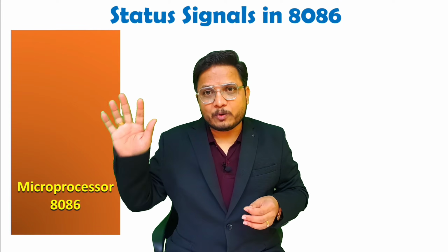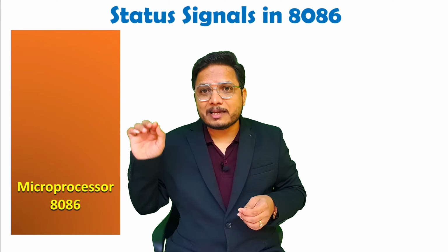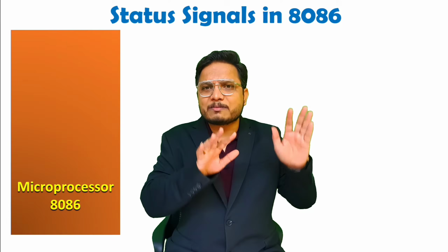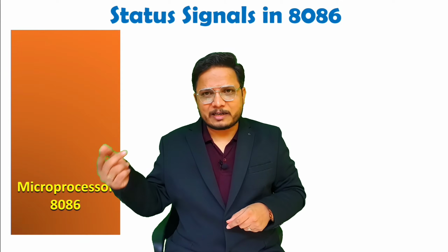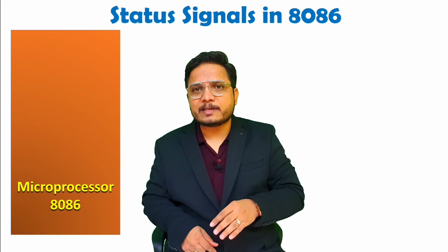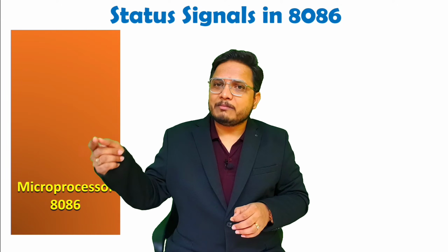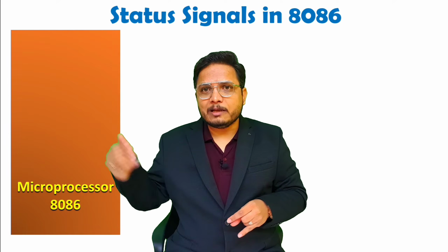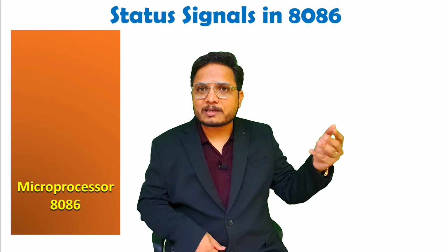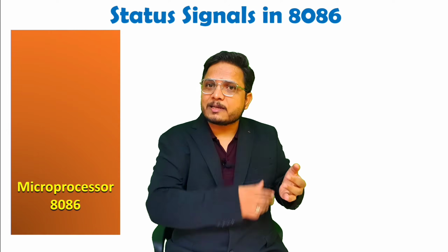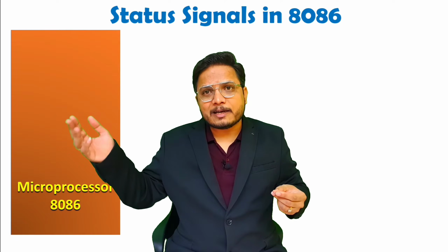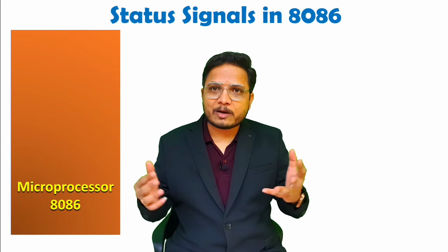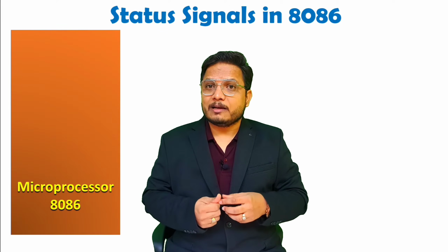The 8288 doesn't need to care about that. The reason is whoever is the bus master will be providing status signals. For example, if 8086 is the bus master, then the bus master's status will get displayed as control signals. If a coprocessor is the bus master, then the coprocessor's status signals will get translated into control signals. That is how it works, right?